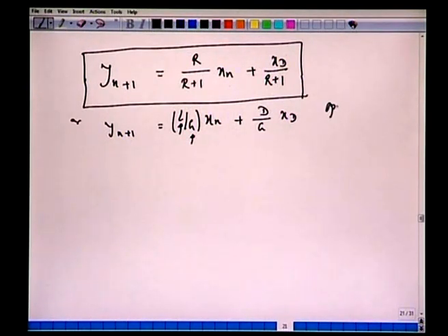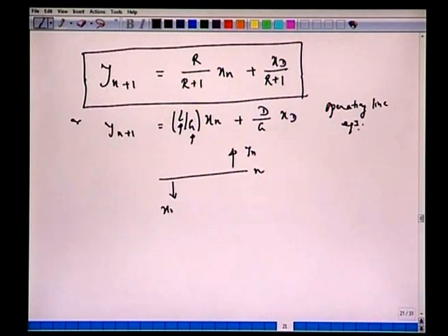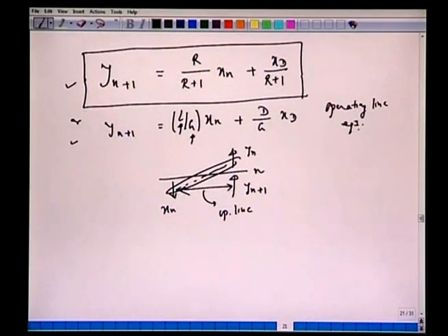We have the operating line equation for the rectifying section. What does it do? We have stage n here, so this is y_n and this is x_n; the two are in equilibrium, that's a tie line. And between y_{n+1} and x_n, the operating line, given by this equation or this equation, does it. It connects the mole fractions of the two streams: the liquid leaving here and the vapor arriving at this plate. So we made that envelope to obtain these equations.